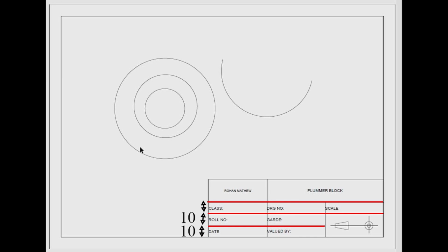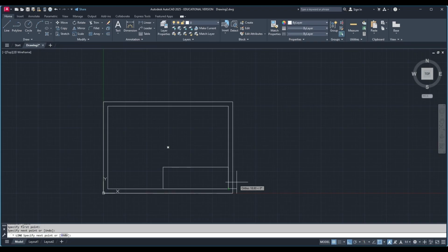So you see here you have other three offset lines which I'm going to draw. For that, I'm typing the offset command here and hitting enter. Now I have to select the distance, which is 10 mm here also. So I will type 10 mm and hit enter, and select the object and move inside one time. I need to move basically 3 times. Okay, second time. Then hitting enter, again selecting that line and moving like that. Then I am hitting the escape button to come out of the command.